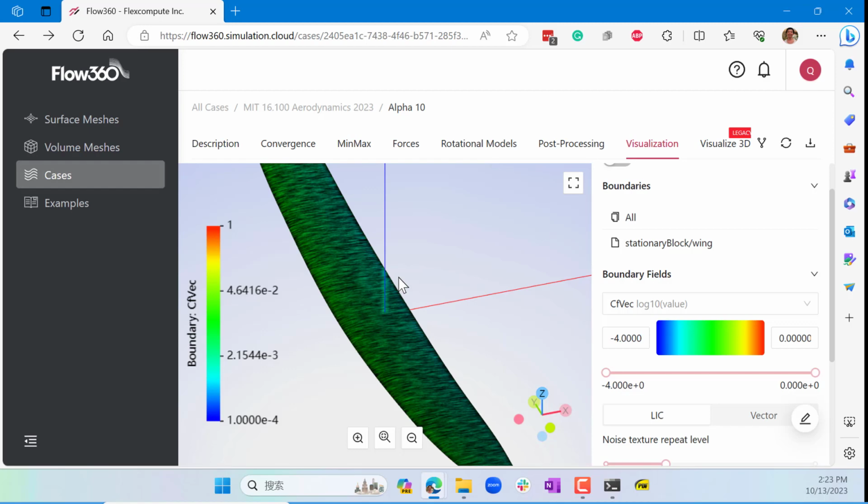So the skin friction is the wall shear stress, or the frictional force per unit area, non-dimensionalized by half of rho u infinity squared, right? So that's what CF is. Now, in our two-dimensional analysis in the lectures, CF doesn't really need a direction, because in 2 dimensions we know the viscous shear stress is tangential to the wall, right? Once it's tangential to the wall for 2 dimensions, we don't need a direction.